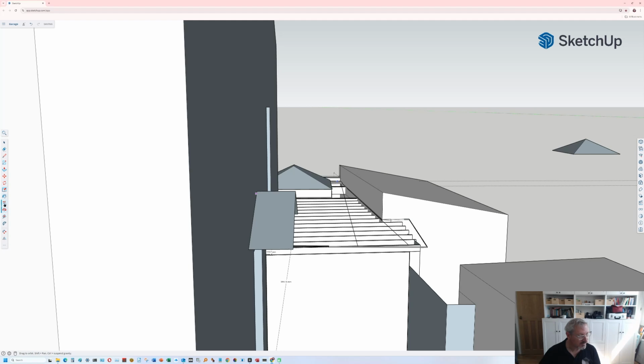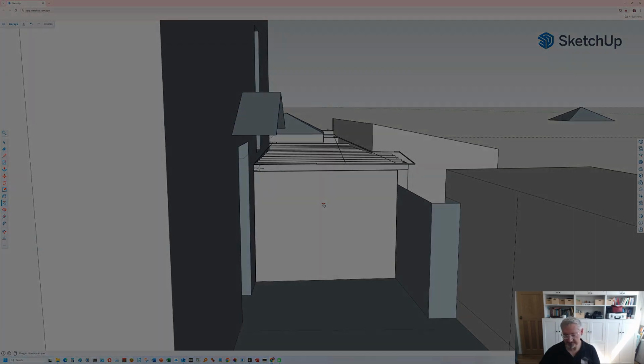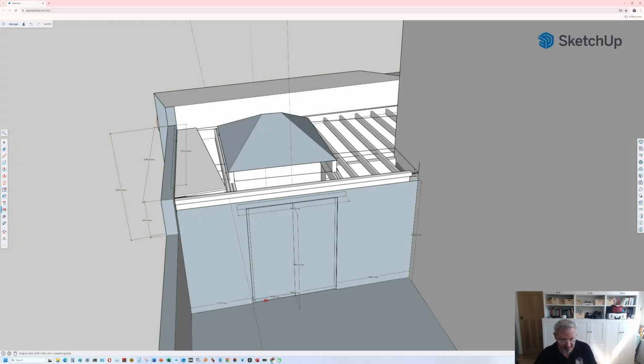So that will take all drainage water. I want these doors to be at ground level rather than a step in, and so I'm going to have a drainage channel all the way along the front here, and there's going to be a drain pipe that comes down here, and there's going to be a gully along this bit with lead lined against the wall, so that there's a bit of a drop into a gully from this way down, and there's some drainage down that way.